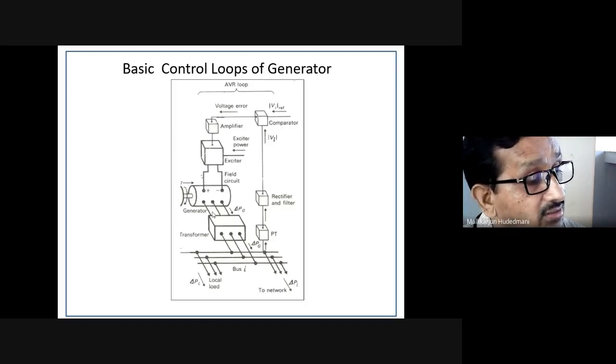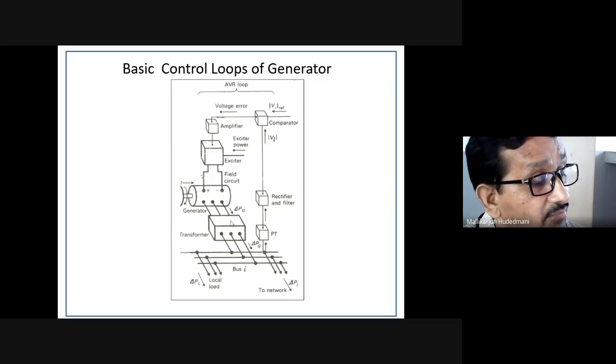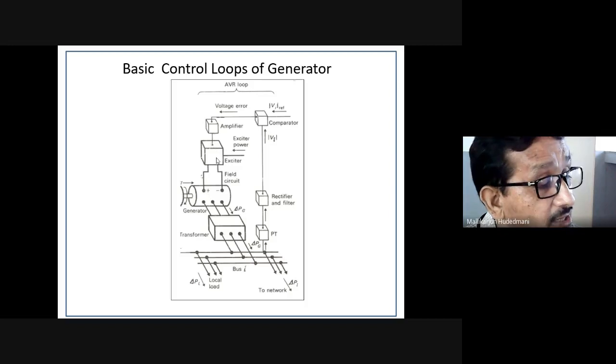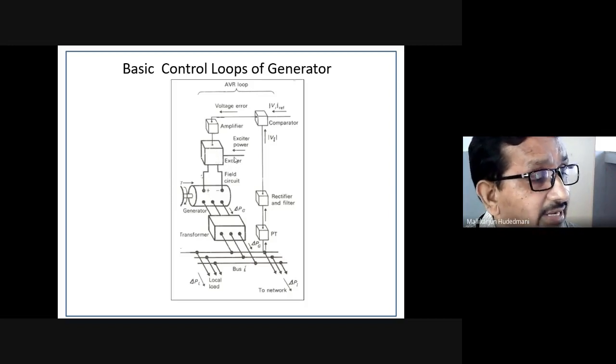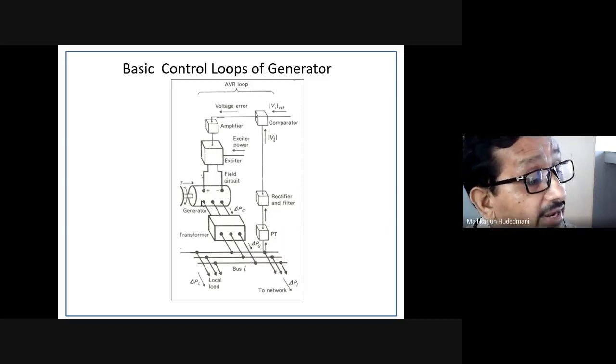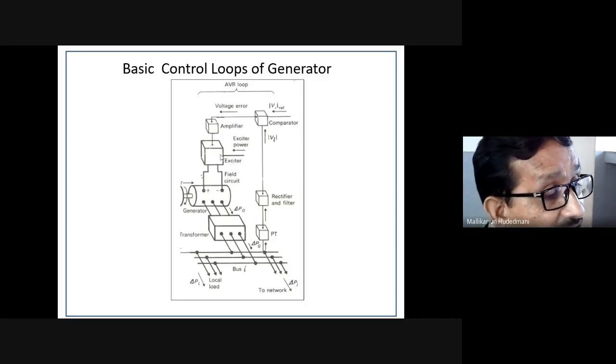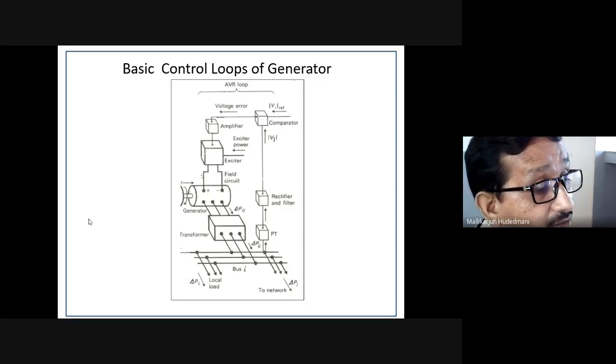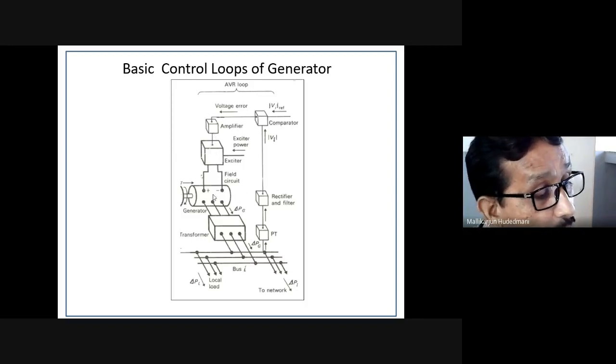No matter, in a conceptual thinking of it, we require the field poles of the synchronous machine be excited for appropriate electromagnetic induction to occur. DC power supply has to be connected to that. That DC requirement of the field is processed and delivered by the exciter. So for this you connect and deliver it. To deliver and regulate, increase, decrease, that is done by a signal acting on this controller by a previous decision process, which is based on what is the actual output it is throwing out to the grid.